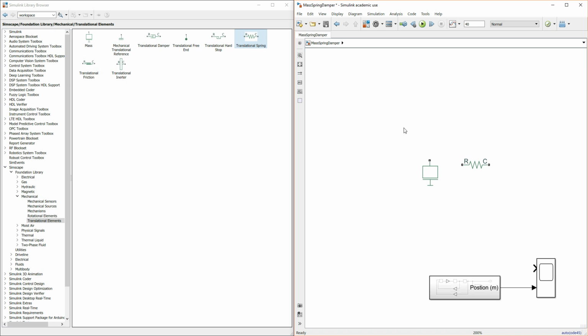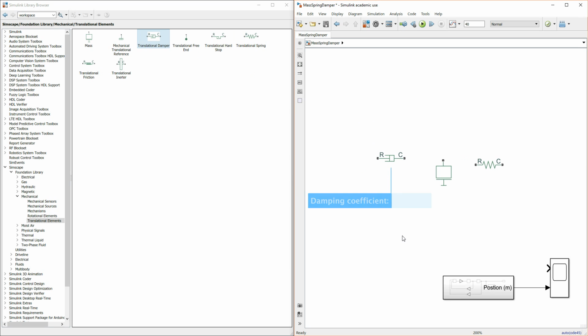Don't worry about the rates. We're going to set these by variable. And I'm going to drag and drop a translational damper. So what we've got now is the zeta value and spring stiffness all predefined within these blocks. This is another reason why I love MATLAB so much, because they've looked at the reoccurring elements of something that you're building, and they've said, right, these things occur, we can put these into translational blocks.